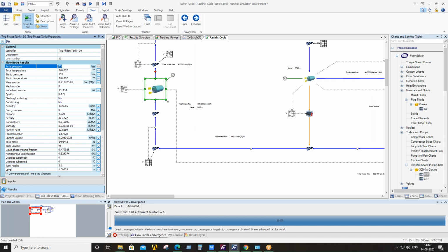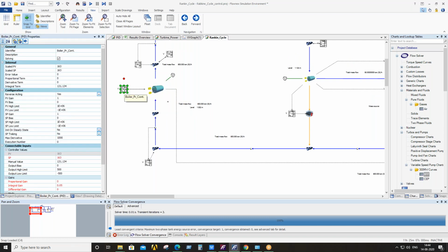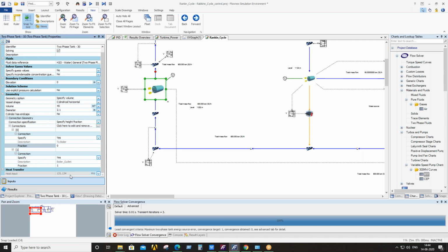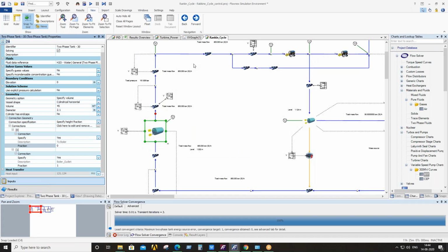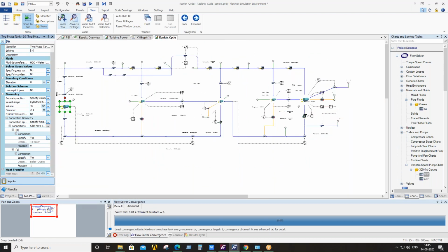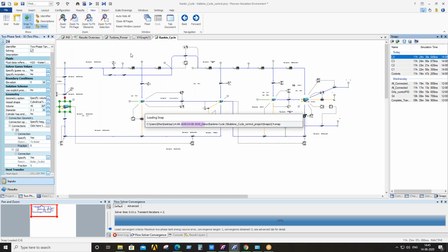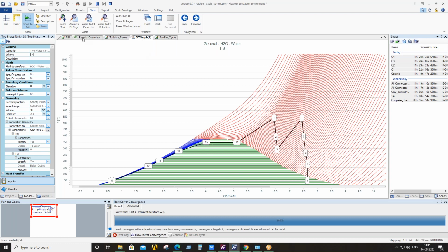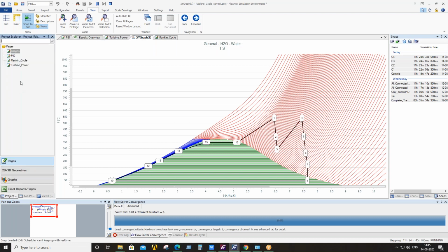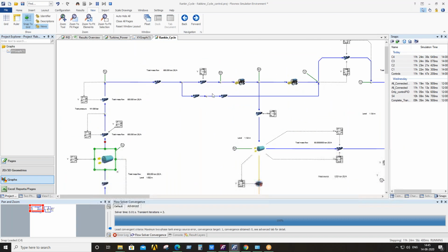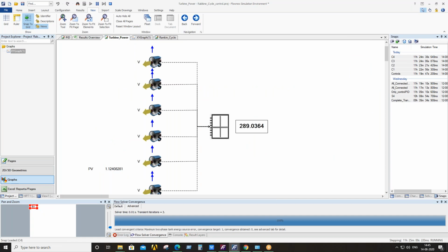In the boiler we have to maintain the pressure around 163 bar, and a controller maintains the pressure around 163 bar, giving heat to the boiler of around 131.134 megawatt. So that completes our cycle. If I run this model, you can see from the graphs the parameters are changing, and you can see the total turbine power output.